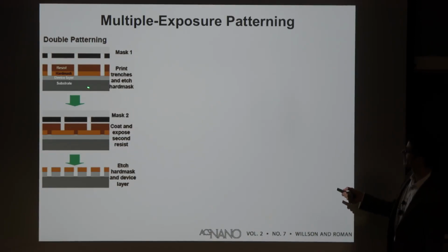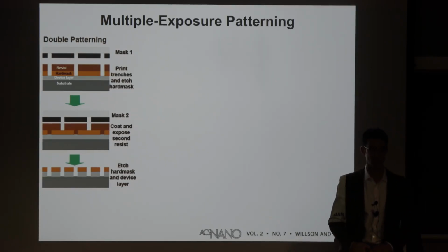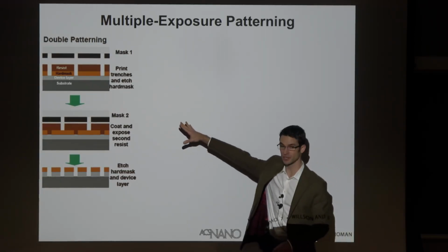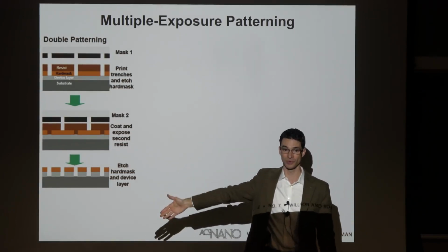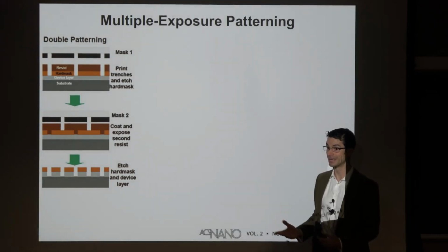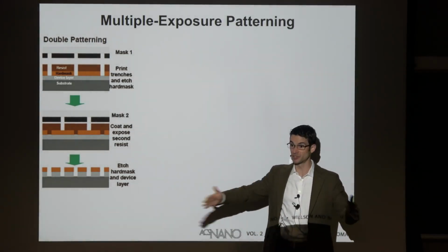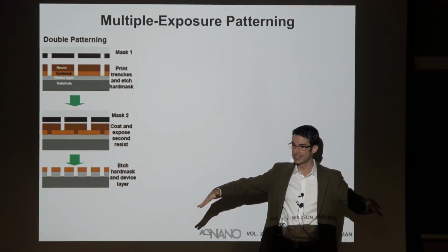Now, why couldn't we just take the same photoresist film and then switch out the mask or move the mask over by a few nanometers to make the other pattern? Here we had to coat a brand new photoresist film. Why couldn't we use the same one and just do the exposure twice? Yep, because it was already exposed. Yeah, so it was already exposed in the edge regions. Where we wanted the exposure, that's fine, but where it diffracts, that's bad, right?